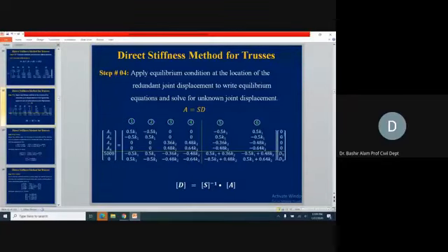Similarly, if you come here, D1, D2, D3, D4, because of the hinge condition, these displacements were understood and were 0 just by observation. At joint 3, D5 and D6 were unknown, so we are now writing this with their appropriate terms. This stiffness coefficient matrix, the 6 by 6 matrix, we already generated, and you know the addition procedure by which we form it from the elemental matrices. This way we can now find the unknown joint displacements.